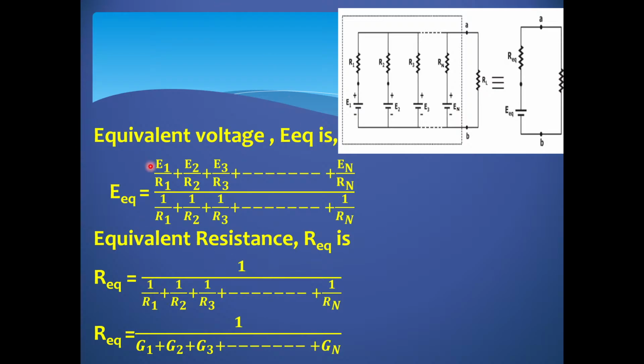These are the formulae you have to use if your circuit resembles the Millman circuit. Millman circuits mean you have all parallel-connected voltage sources along with internal resistances, or a combination of voltage sources along with current sources. Then you can apply Millman's theorem if it is not specifically mentioned in your question.